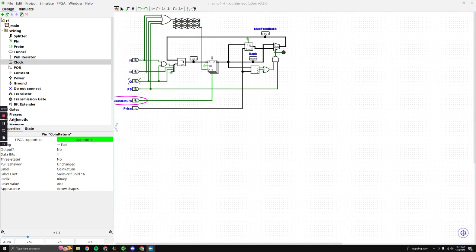Now, to go over some different scenarios within this circuit, I'm going to first talk about a phrase that we learned in our unit videos when creating the circuit, and that is asking ourselves the question, what tools are in my toolbox? How that phrase helped me during the making of this vending machine was realizing what we've made over this course. What's in our toolbox is everything that we have readily available to us, and that can be our adder, our subtractor, registers, our comparator, our muxes.